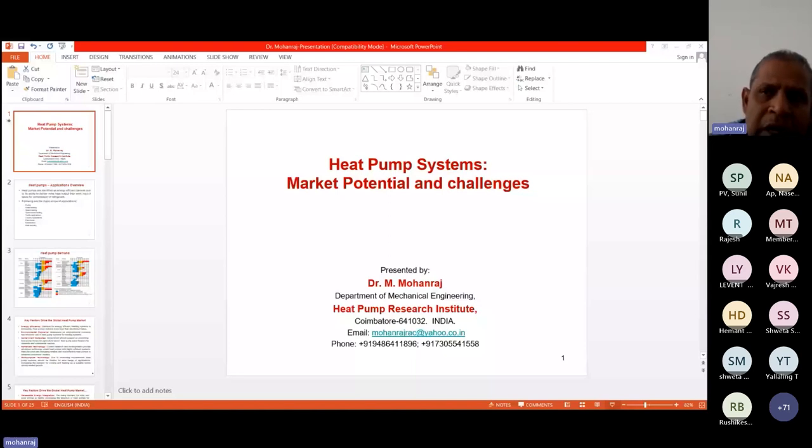With carbon dioxide, it works on a transcritical cycle. So partially it is below the critical point and partially above it. Above the critical point, we need to go for a gas cooler. This will be another big challenge, to go for such modifications. So for replacing R134A, an R290 and R600 blend, not pure R290, is the best option right now. For new systems, it is better to go for pure R290, propane systems.